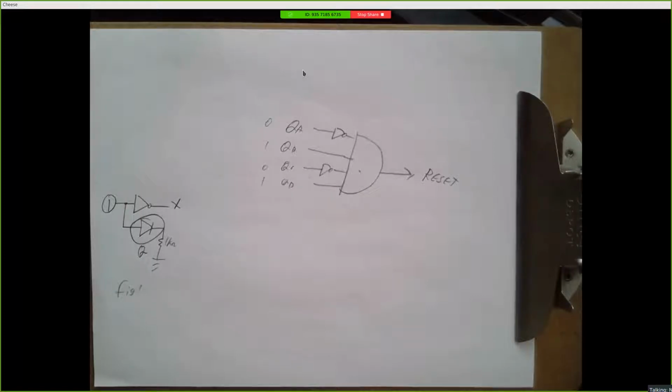For example, we needed to have pin 12 connected to pin 1 on the counter. And if you don't do that, it's not going to count all the way to 10, right? And I don't know if that was just an omission or what, but double check your wiring diagrams as you're writing them up. Ideally, you're making a wiring diagram before you actually build the circuit, right? But the reality is, a lot of times people seem to build the circuit first and then make a wiring diagram, and that's more error prone because you can miss wires.